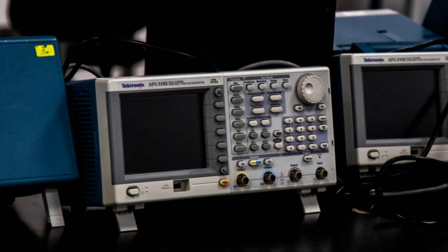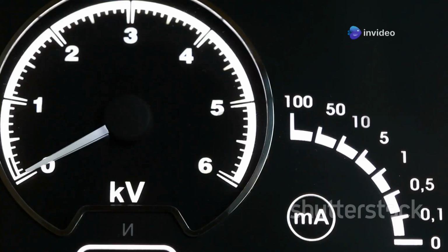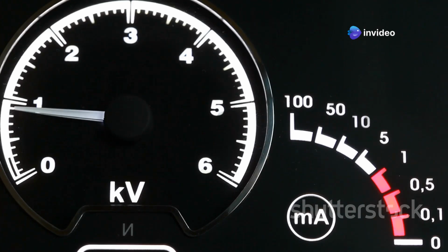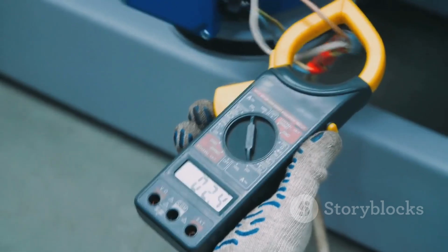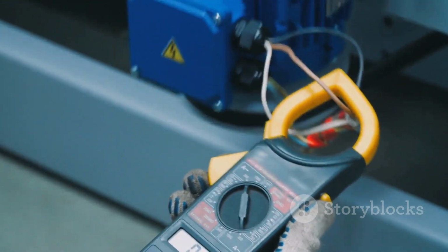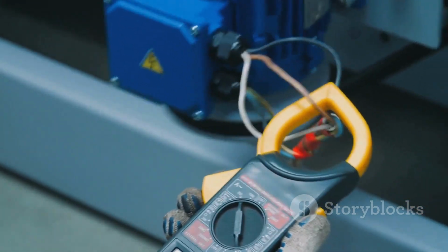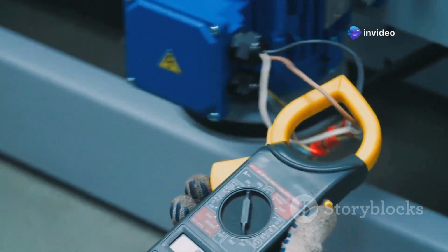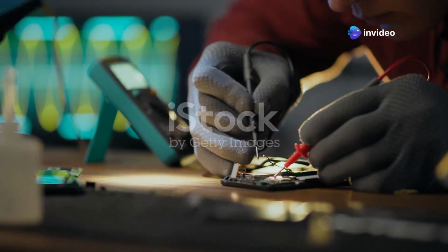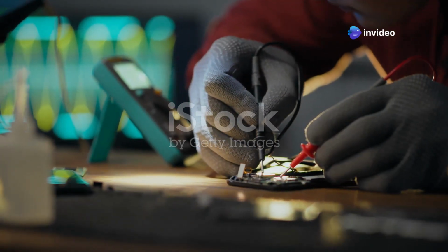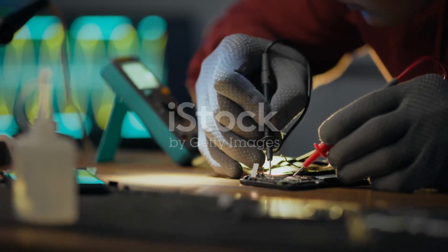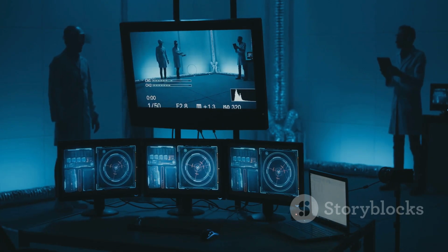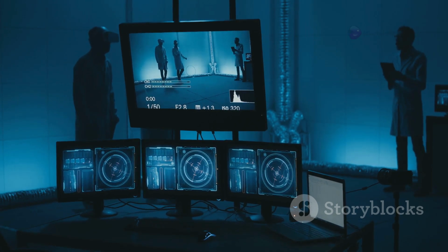Analog signals come in various forms. One common type is the 0-10V signal, which varies voltage to represent different levels of a parameter. Another is the 4-20 mA signal, which uses current to represent parameter levels and is less susceptible to signal loss over long distances. RTD, or resistance temperature detector, is a type of sensor that changes resistance with temperature, providing precise temperature measurements. Understanding these signals is crucial for effective building automation.